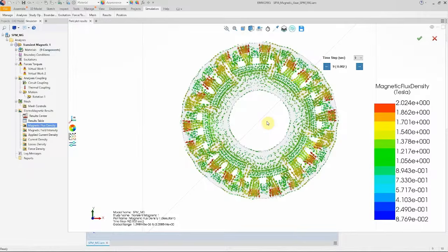The other question is, in an existing magnetic gear design, how can torque ripple be minimized? For minimizing the torque ripple, just like other machines, we can use the skew angle in the rotor, in the inner rotor or outer rotor, or even in the middle ring in the modulation ferromagnetics.